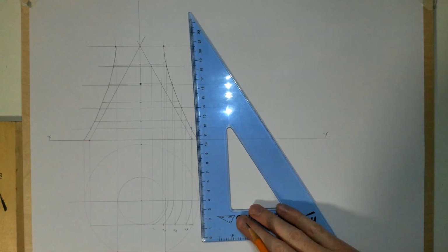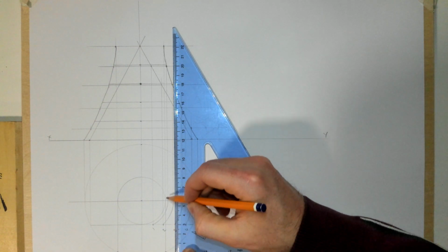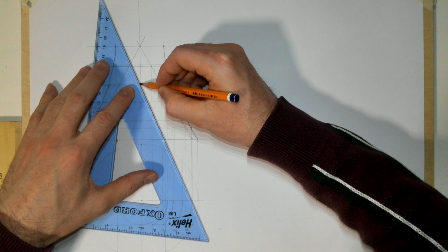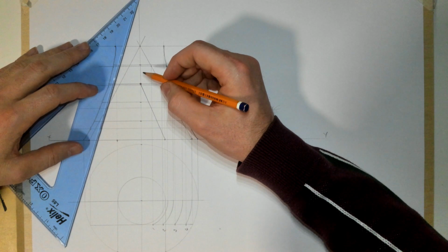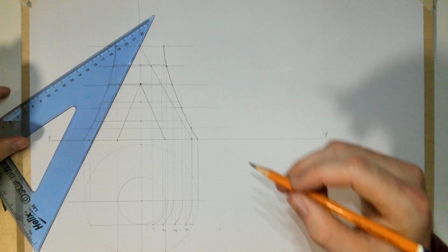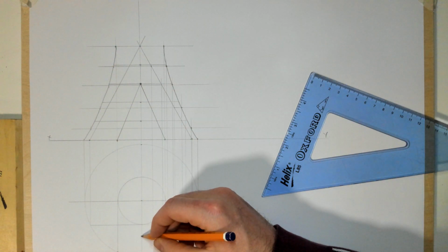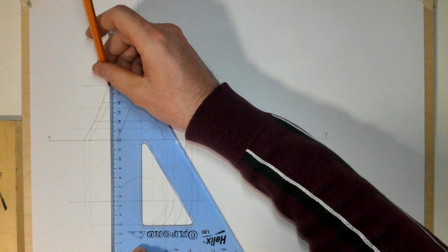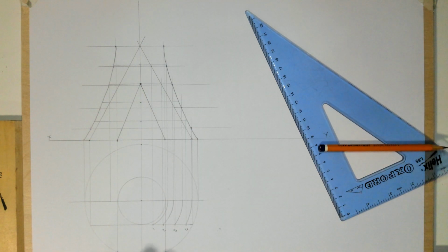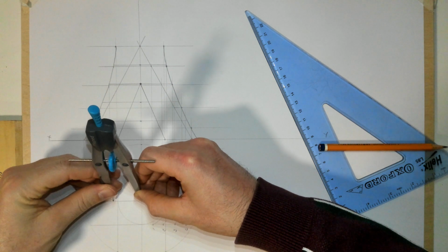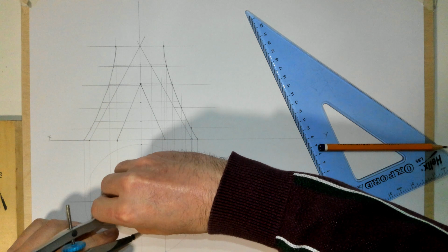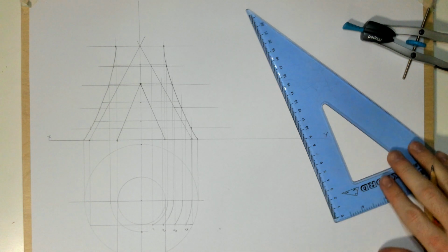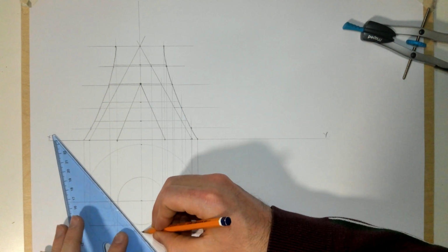Okay, and we know that it goes to those points there, which is that one and that one. And we can draw them as straight lines now in front elevation. Okay, so that's the V found. Now, to get the points here, we bring each one across to the edge, drop it down to the horizontal line, and swing it around then in plan. It's going to give me that line there, or that point. So I can draw in now that V shape. It's 2 straight lines in this view as well.